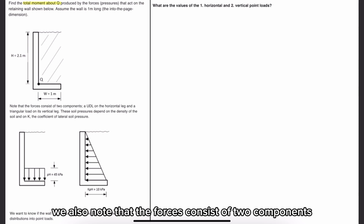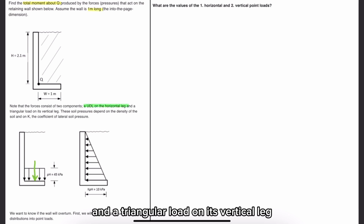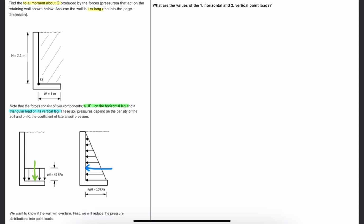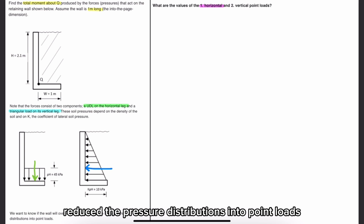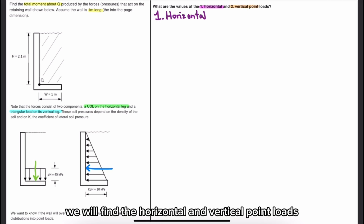We also note that the forces consist of two components, a UDL on the horizontal leg and a triangular load on its vertical leg. These soil pressures depend on the density of the soil and on K, which is the coefficient of lateral soil pressure. Both diagrams shown here underneath display both the horizontal load as well as the vertical load. We would also like to know if the wall will overturn, and this question has therefore reduced the pressure distributions into point loads. Firstly, we will find the horizontal and vertical point loads.